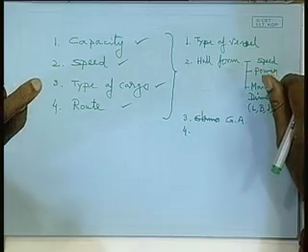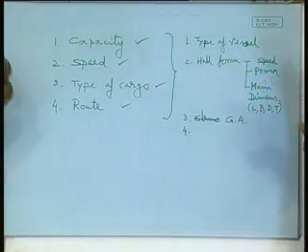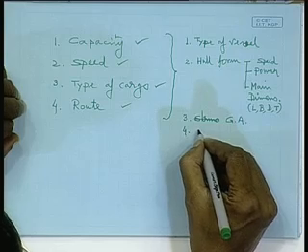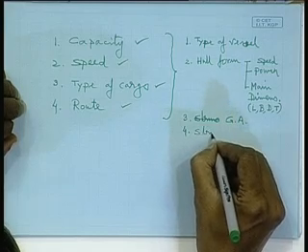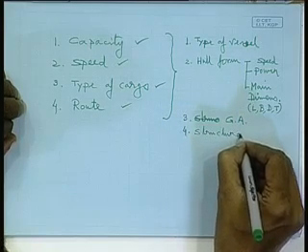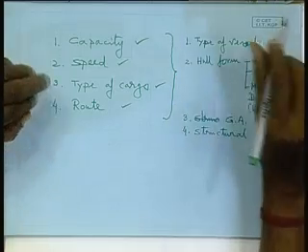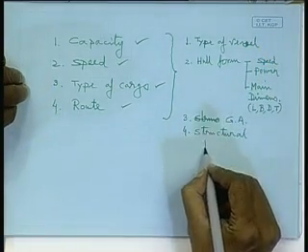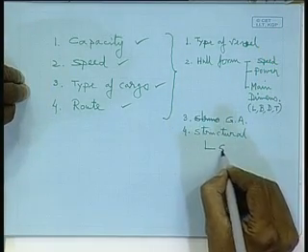And the hull form, at that stage, is only whatever will provide you the minimum resistance. Theoretically whatever you are getting, you come to that hull form, so that the expected speed condition will be satisfied, provided it is providing the required power. Then comes the structural design, and in this structural design, you start with the so-called scantling calculations.